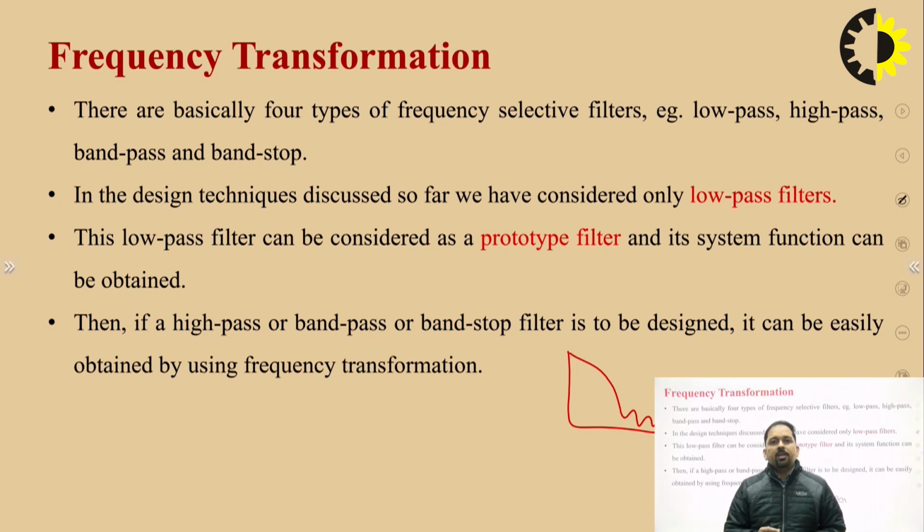So once we are having the low pass transfer function, but let's say being a designer, if someone asks you to design a digital filter which is a high pass, or it's a band pass, or it's a band reject filter, so we need to use the transform kind of approach. So we'll be utilizing the frequency transformation, and we can convert that prototype low pass filter into the corresponding high pass filter, band pass filter, or band reject filter.